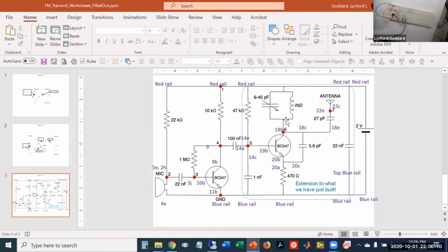So if we just look at this part of the circuit and not think about anything else. If I put charge on the capacitor, and I ordinarily connect this to a resistor, the charge will just flow through the resistor and energy will be dissipated. But in this configuration known as the tank circuit, the electric charge that's on the capacitor wants to flow into the inductor, but the inductor is a device that resists instantaneous changes in current.